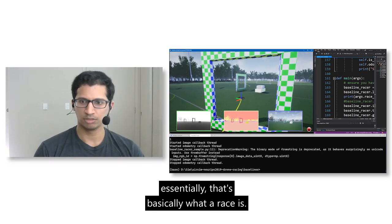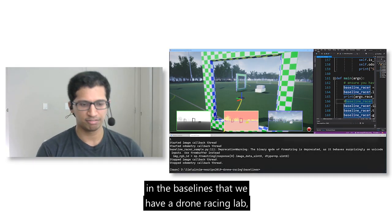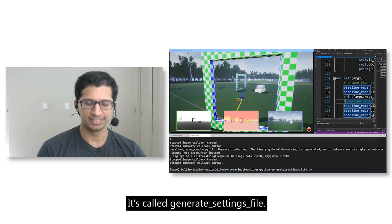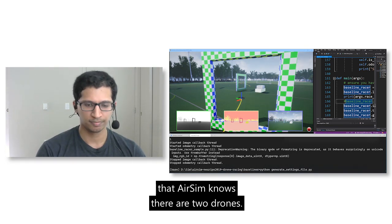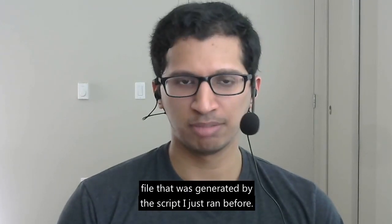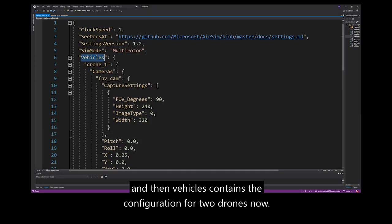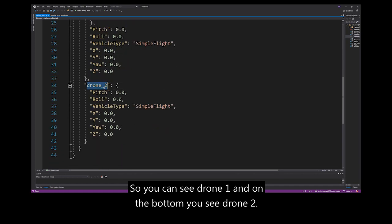Essentially, that's what a race is. So in the baselines that we have for Drone Racing Lab, we also provide a helper script called generate settings file. This script ensures that AirSim knows there are 2 drones. Here we see a sample settings file that was generated by the script I just ran. I have a tab called vehicles, and vehicles contains the configuration for 2 drones now. You can see drone 1, and on the bottom you see drone 2.